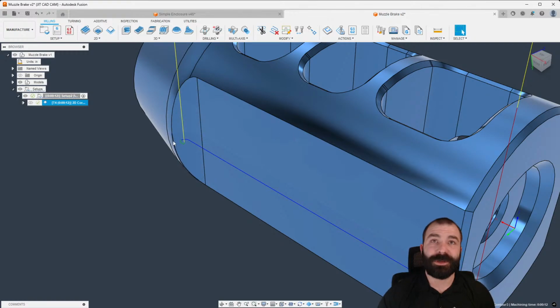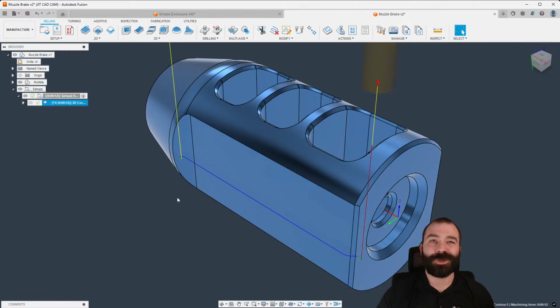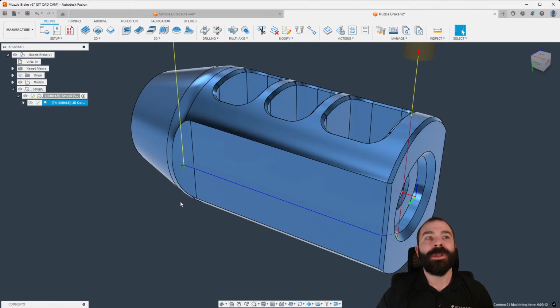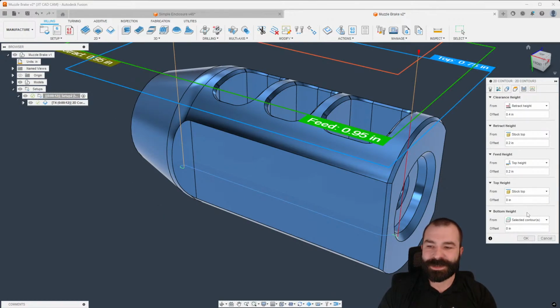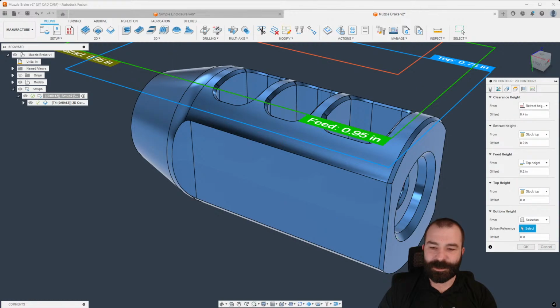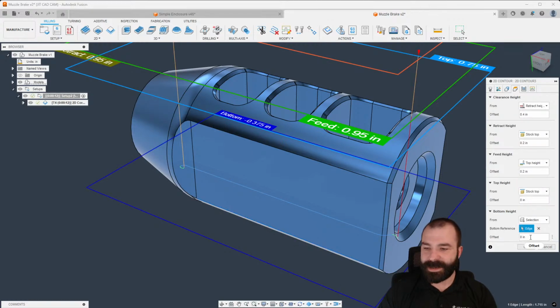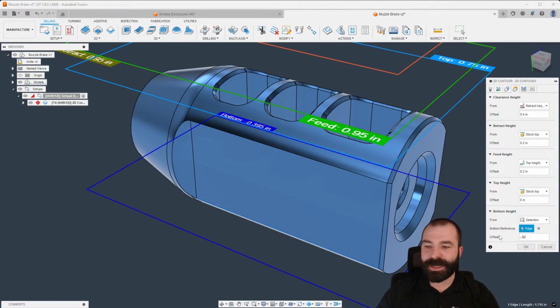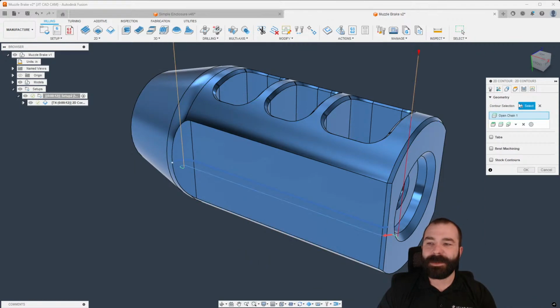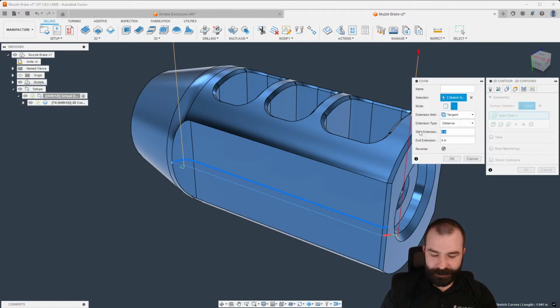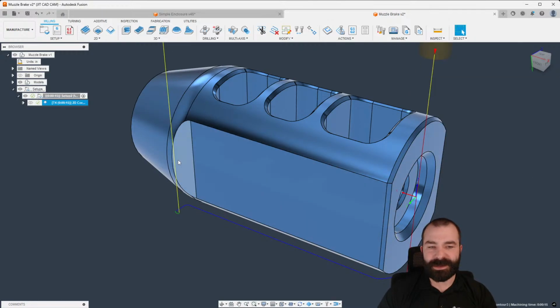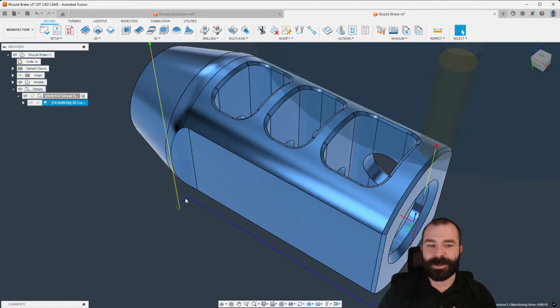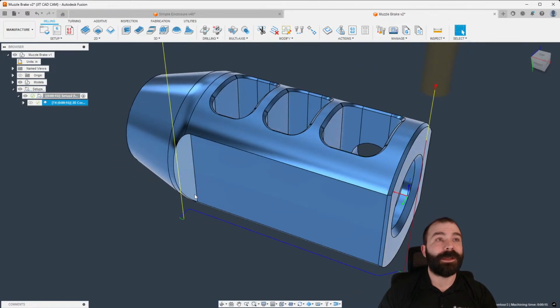Again, we're going to adjust this a little bit more, but by splitting the body and projecting those edges, it's actually helped me out in order to create the geometry to create that profile. Yes, I know we could also lower that down, of course. We may want to go to a selected contour, right, down here at the bottom, minus whatever you're going to feel comfortable with. I'm going to go 20. And then from that, I am going to extend out my lead in and my lead out on this profile. And now you'll see we start to get down to that corner and we've started to lead away from the part, right? Again, another way to look at this.